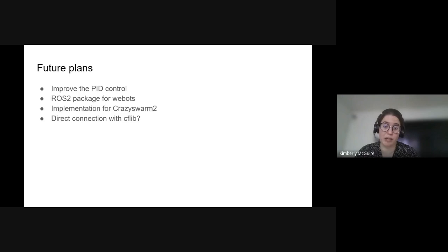It's something that you can implement. You can, for instance, also take the C-based controller, and you can take the wall following state machine from the Crazyflie firmware itself, which is also compartmentalized. It's written in a way that you can take that piece of code and import it somewhere else, as long as you provide the multi-ranger inputs and the yaw, and as output it has the velocity that you want the Crazyflie to have.